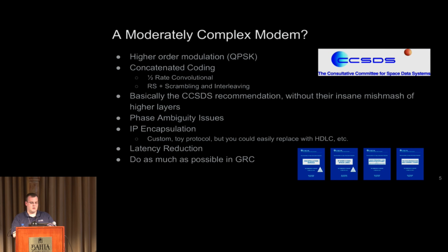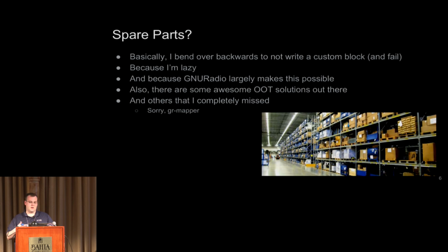Latency reduction, as I said, and I'm lazy. I don't like to write C++ code, so I try to do as much as possible in GRC. So spare parts, that comes back to that last point: I'm trying to do this as much as possible in GRC with existing blocks and avoiding writing my own blocks. I do fail at that, but I do pretty well, and I'll show you where we had to write a few custom blocks and use a few out-of-tree modules just to make things simpler. GNU Radio is great because this is possible.